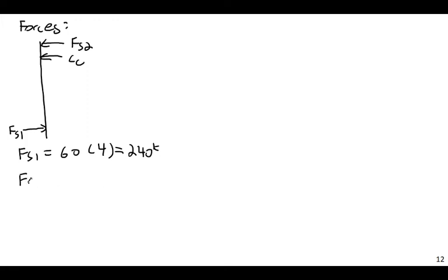FS2, again, I'm going to put in a fudge factor to make sure I'm not double dipping between compression steel and compressive concrete. This is going to be 44, so basically I subtract the stress that's present in the Whitney stress block. 44 minus 4.25 times 4, and this then comes to 159.1 kips.